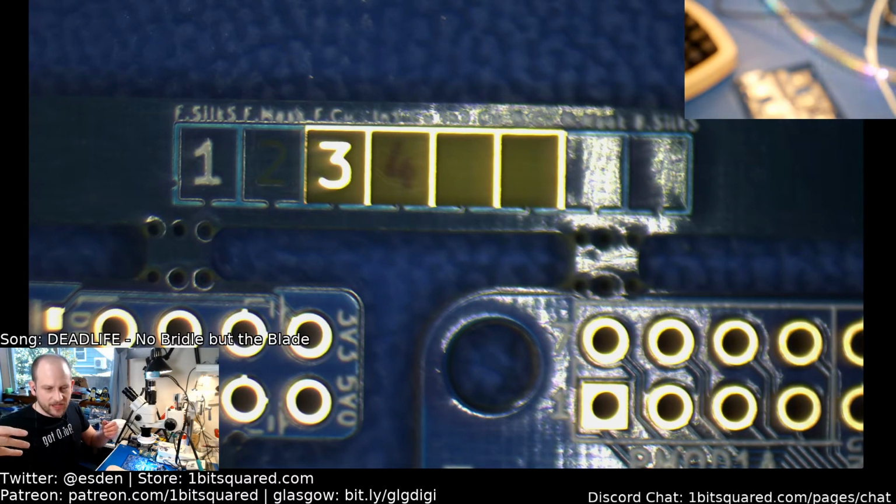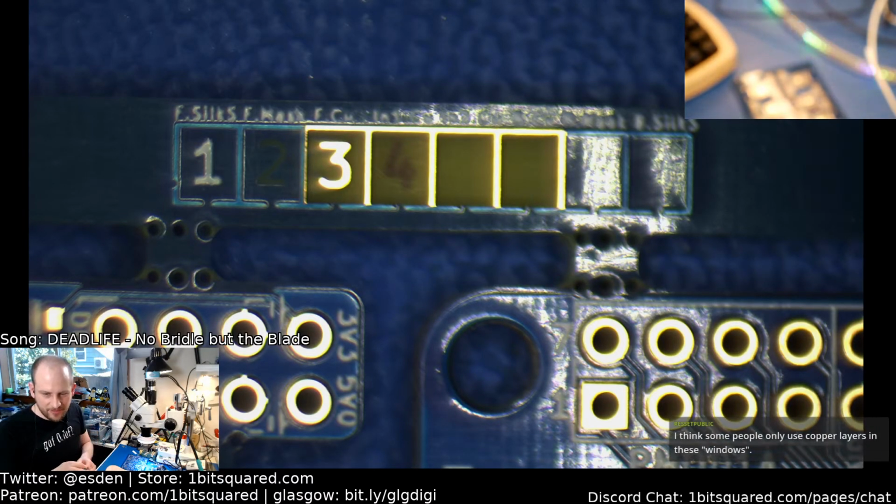And then after they expose it and etch it, they put on pre-preg, a very thin, pre-prepared, pre-soaked fiberglass material with copper on the outside to add the top and bottom layers that they can etch in another step.